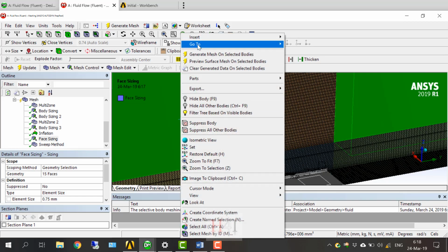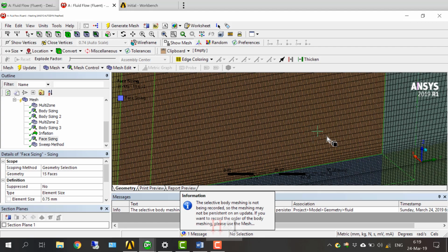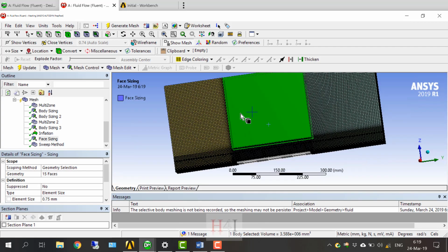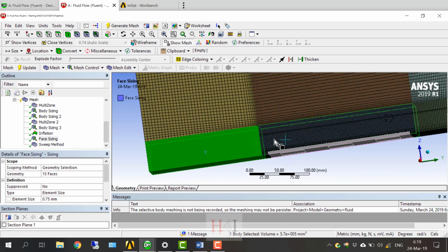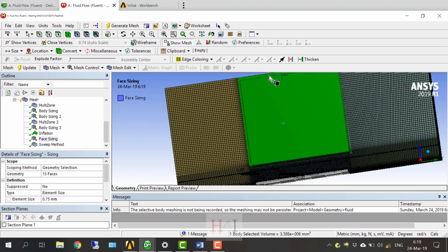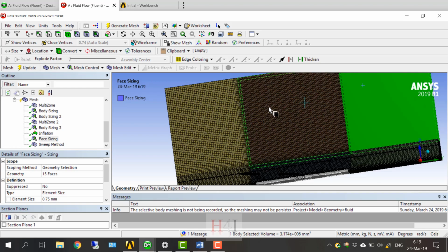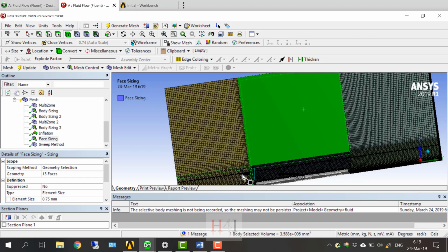Okay. Now meshing on these bodies. Now everything is okay. We have complete mesh. These bodies we can control better by using sweep. This body will be swept from this surface to this surface. We can create the bias to get larger away from the heatsink, and this body can be swept from the bottom surface to the upper surface, and use bias to get it larger away from it. These two bodies will follow these two sides because this is already meshed, so I don't need to choose bias.